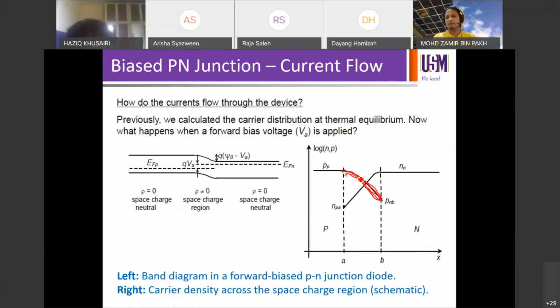But if you compare this with the profile change in the quasi-neutral region, this is going to be very, very small. Delta J, if you're talking about this, is going to be much steeper in the quasi-neutral region, so this one becomes very, very small, like there's almost no change. It's just that when we were learning about the depletion region profile, we had to exaggerate the profile so that you understand the change.